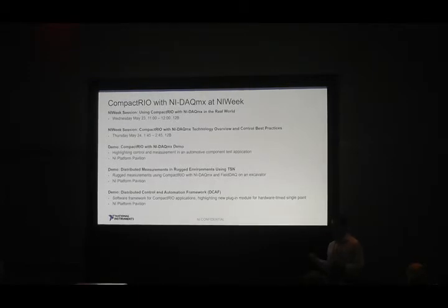So I showed in the demo being able to set up the modules in MAX or the LabVIEW project. There is a third option which I didn't discuss, but there is a shipping example for, which is programmatically changing the modes on these. You can specifically choose whether they're by slot, DAQmx, FPGA, real-time scan, whatever mode is specific for that. So programmatically you can set this up appropriately. And we do provide a lot of the same features today in terms of identification, especially within DAQmx, to understand what the module is and collect some of that data. In terms of whether it's easier or not, I don't necessarily know that we've made it any easier. I'll open up to some of our software folks in the back to see if they have any thoughts, but a lot of that capability is certainly possible.